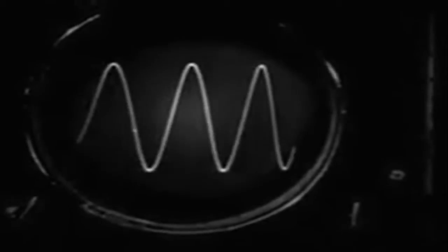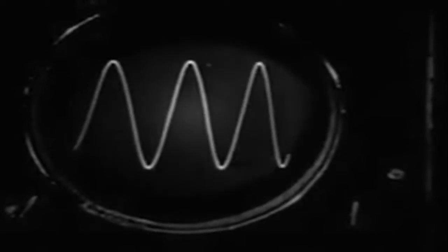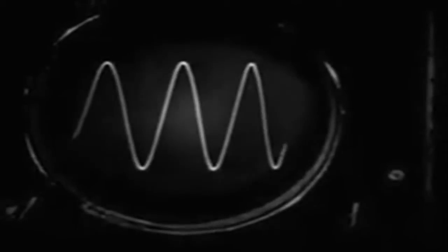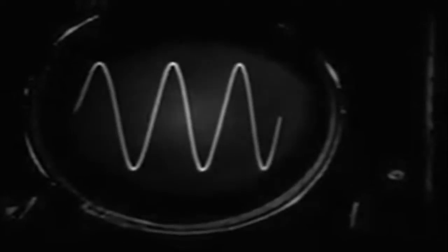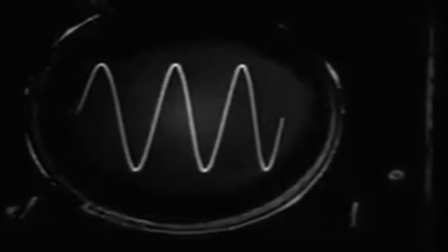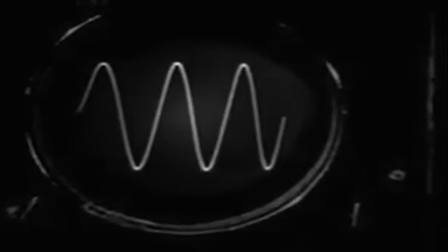Now, on the screen, we get a direct frequency comparison. The number of cycles on the screen shows the frequency ratio of the signal being compared to the line frequency. For example, supposing the line frequency is 60 cycles, we set the frequency to 60. If we have 3 complete sine waves on the screen, we know that the frequency of the test voltage, as shown on the screen, is 3 times the line frequency, or 180 cycles.